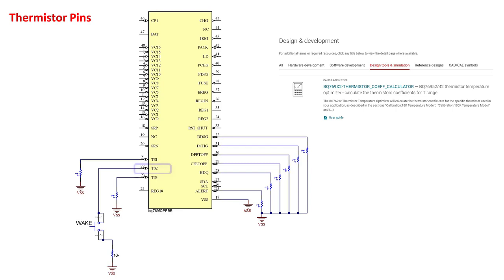The TS2 pin is unique in that it is also the wake pin for the device. If shutdown mode will be used in an application, it is not recommended to connect a thermistor to the TS2 pin because this will prevent the device from being able to enter shutdown mode and can get stuck in a soft shutdown state. See the TRM for more information about soft shutdown.